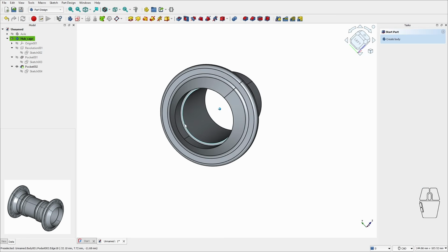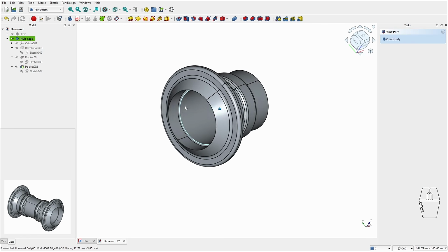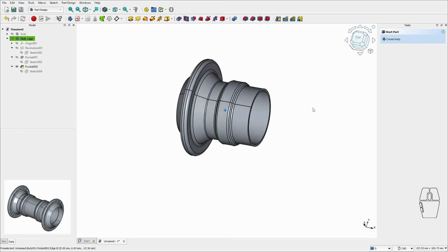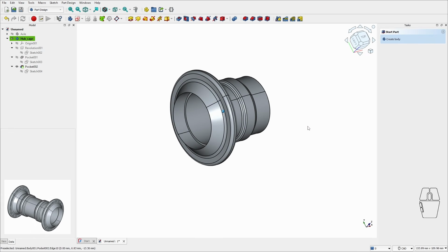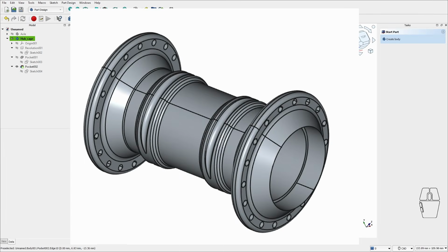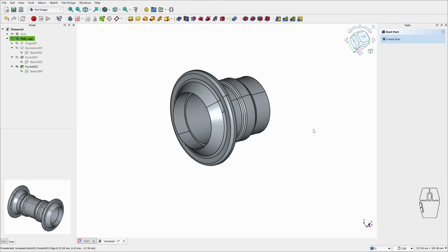You should now have the cavity that will hold the bearing along with a smaller hole that goes all the way through the hub. Before we create the symmetry to get the missing part, we're going to make a small relief cut on the central bump as shown in this diagram. As you can see, the relief isn't a simple shape, so we'll use an ellipse to create it. The first step is to create a datum plane at the center of the bump so that the relief cut is perfectly centered. The ellipse will be drawn on this plane.